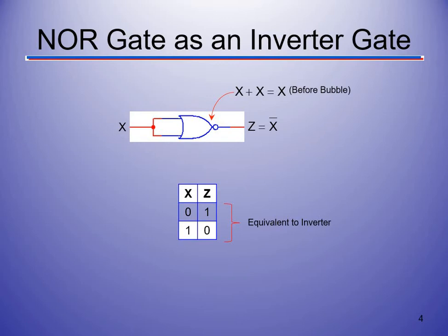Okay, just like we did with NAND gates, we can completely redraw AOI logic for this. So if we want to use a NOR gate as an inverter, we will send one input into both inputs of a NOR gate. This is a 2-input NOR gate. X will go into 2 places. So X or X is X, and then we put a bar over it, so it becomes not X. So that is identical to how we use a NAND as an inverter gate, sending the same signal into itself. So nothing really new on that one, except we're using the NOR gate.